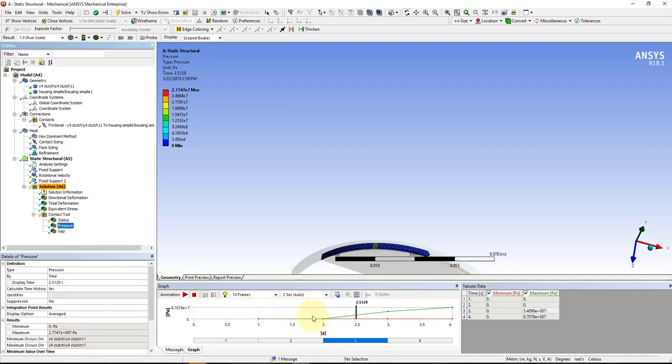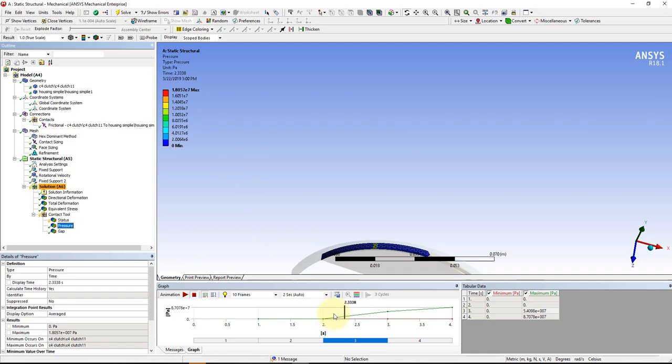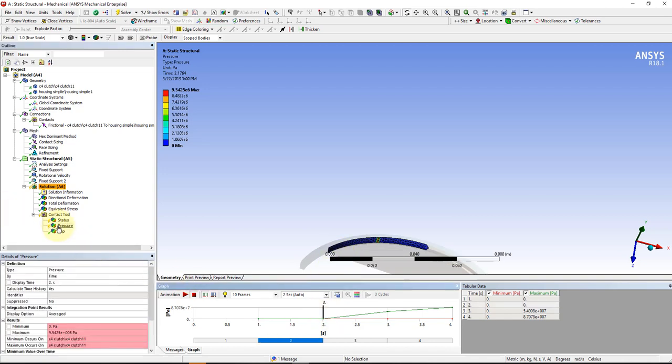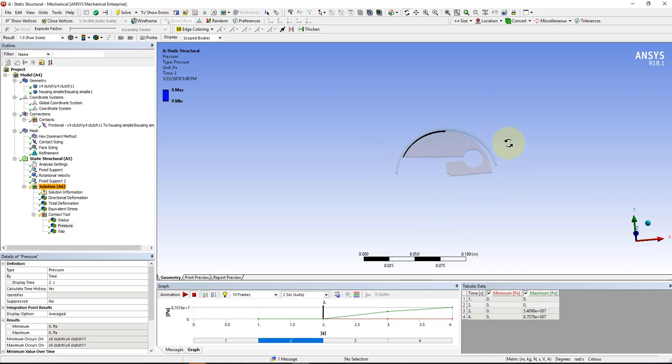And it will save some values at the in-between points generally, so there's some change. It'll automatically interpolate as it does the nonlinear solution. So you can select these in order to help approximate that value there. So we're getting pretty close. It certainly dropped off the pressure quite a bit, and you could continue moving that along to see where that limit is, and then maybe rerun something a little bit between those speeds. Right, so hopefully it gives you a little bit of an orientation about how to approach this, as well as some additional experience with the mesh, and we'll